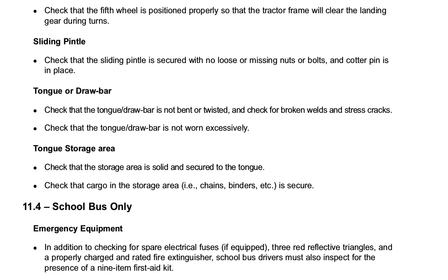Tongue storage area. Check that the storage area is solid and secured to the tongue. Check that cargo in the storage area, chains, binders, etc., is secure.